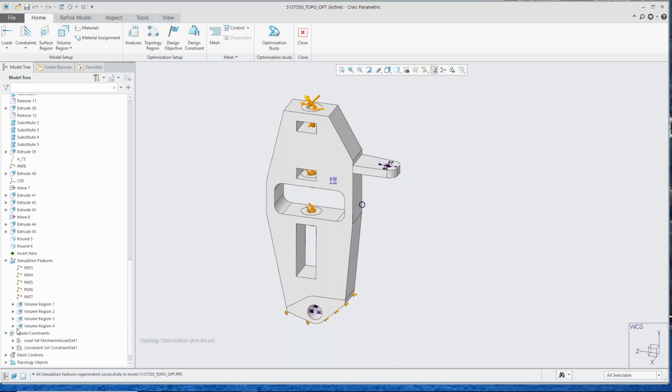You can go ahead and hack at the other stuff, but leave these guys alone. So we want to leave that tab there. We don't want it to be all whittled away to nothing. Same with the bottom area down here, because there's a couple of surfaces that other components are relying on to be there. We don't need those to be removed. So we'll specify volumes as kind of like keep out areas. Don't mess around with that.